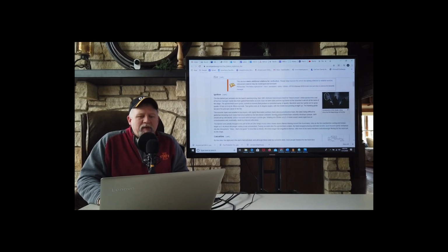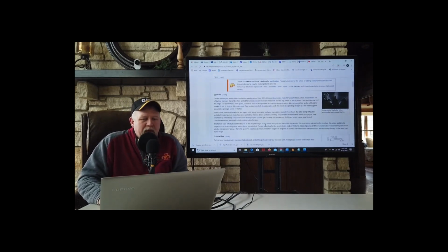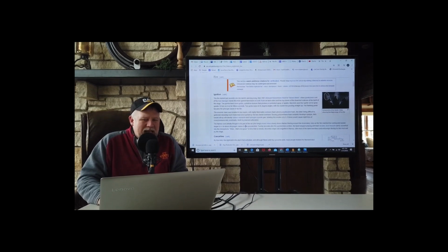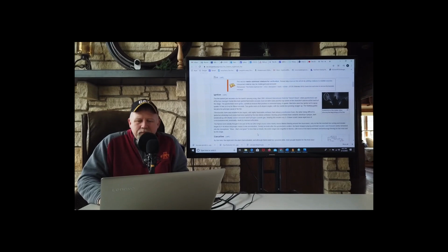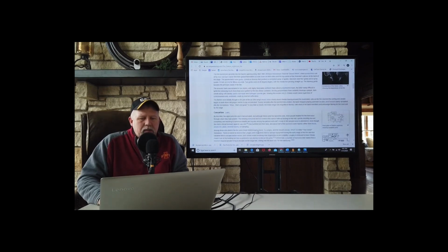The polyurethane foam was incredibly prone to fire. And when it burnt, it develops a dark, deadly smoke, produces carbon monoxide, obviously, and hydrogen cyanide gas. Apparently, if you only inhale this a couple times, it's going to cause a rapid loss of consciousness and death by suffocation. All right? It was the wrong stuff used in the wrong place. All right?